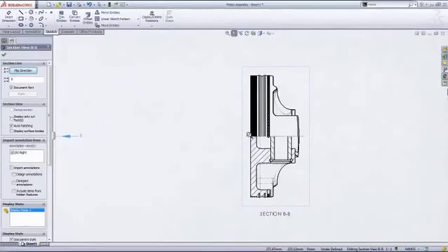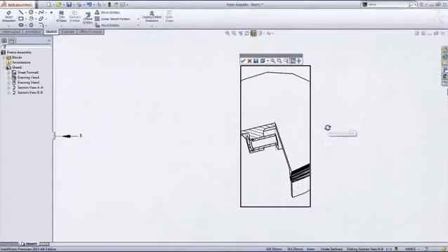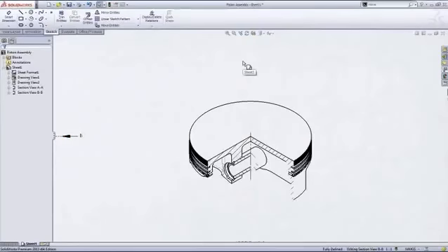view. To do this, you can select any view, and in the heads-up display in drawings, there's an option to rotate it. You can even choose predefined views and models like isometric. Then, if I click the OK button, the view will be saved in this position. Now, the line work in this view doesn't look that good, and this is the second part of this trick to make these look nice.